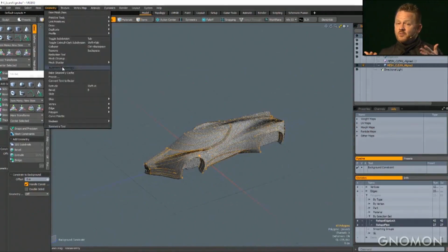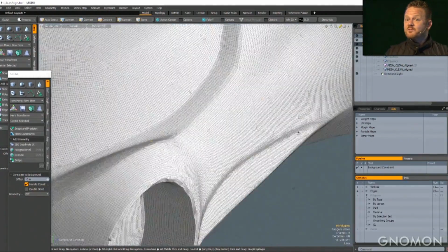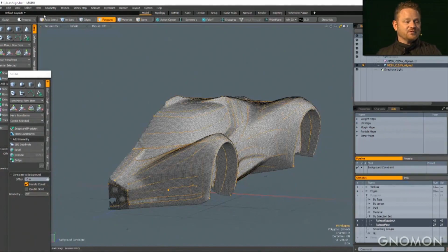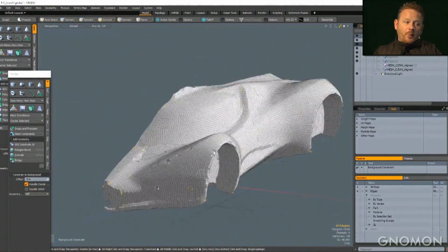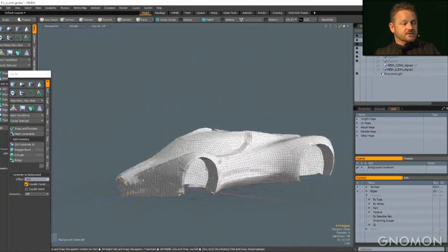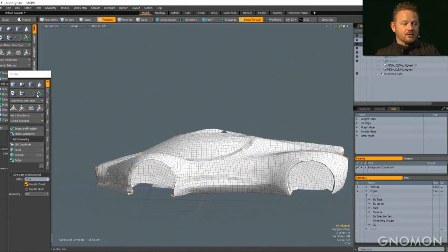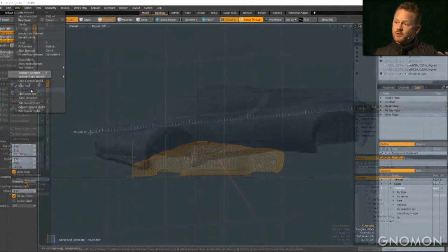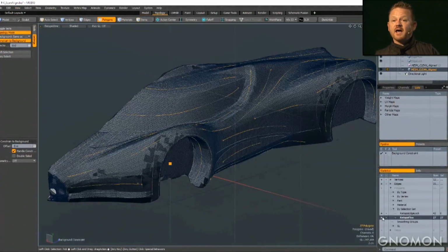And the tools, we're seeing that guys are getting a lot of output through this. And depending on the scale of the model, because some of the settings need to be dialed down or up depending on how large the model is. But basically, it helps you decimate the model, shrink wraps a quad quilt over the whole thing, and then I take that and